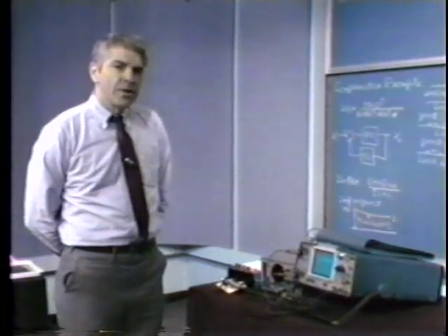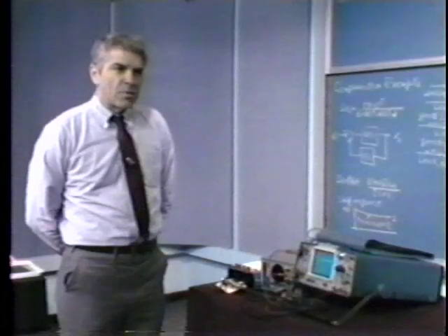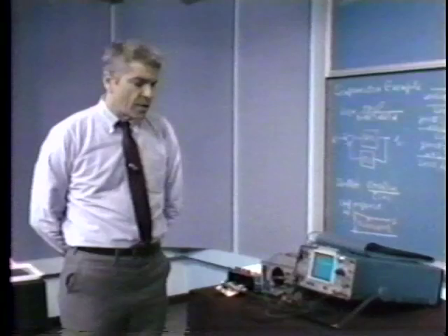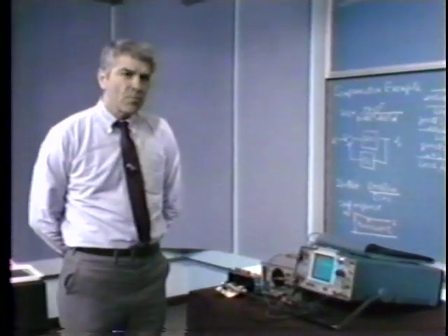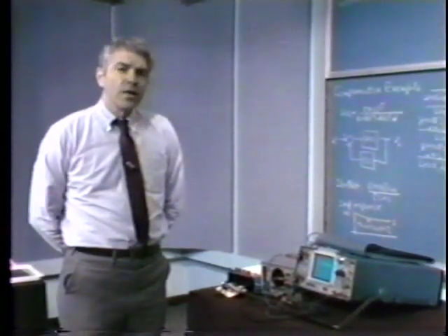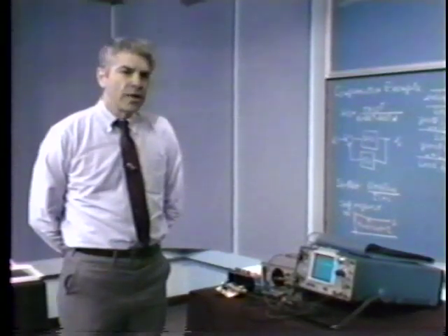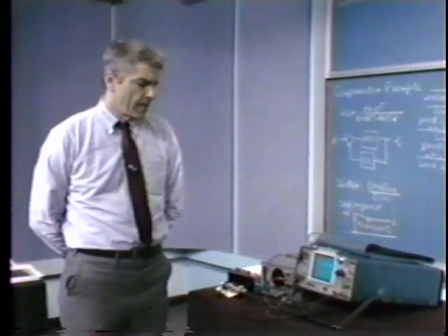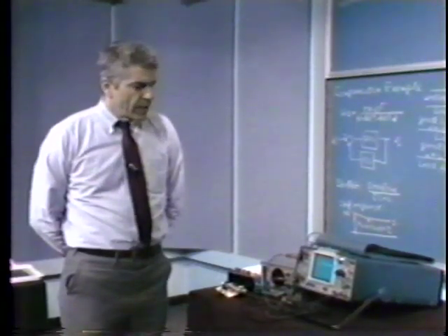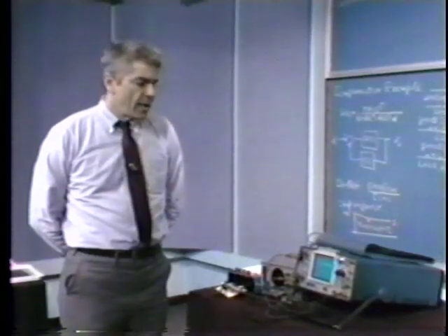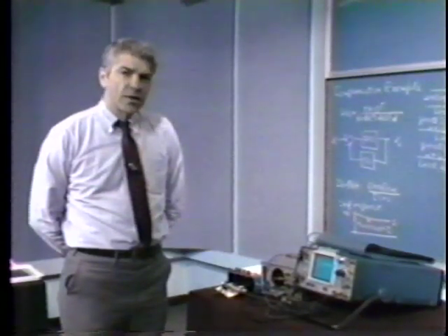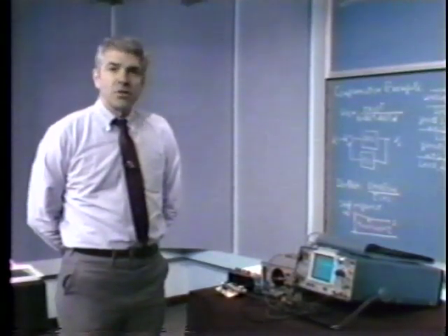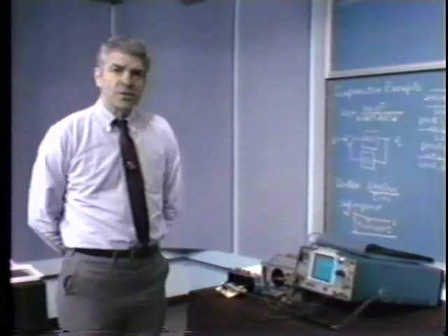But let's think a little bit about the effect of crossover frequency on the oscillation associated with the step response. We said that from the Bode plot, we find that this system crosses over at about 2.4 times 10 to the 4th radians per second. If we divide that number by 2 pi, we get something like 4 kilohertz for the crossover frequency of the system.